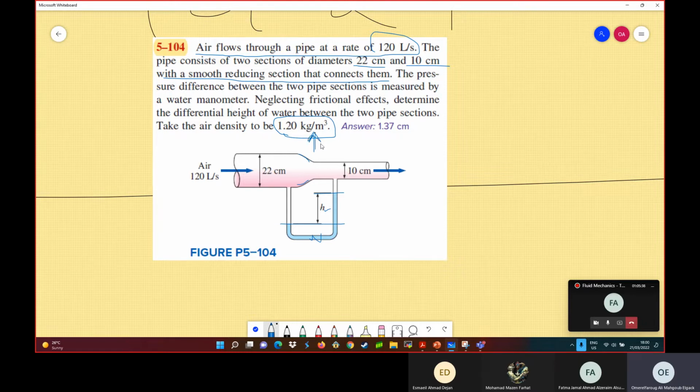If the flow is compressible, then we have a different value of density here and here, and we cannot apply the Bernoulli principle. But when he gave you only one value, he's telling you indirectly that this flow is incompressible and you are okay to use the Bernoulli equation. But now let's double check to make sure.